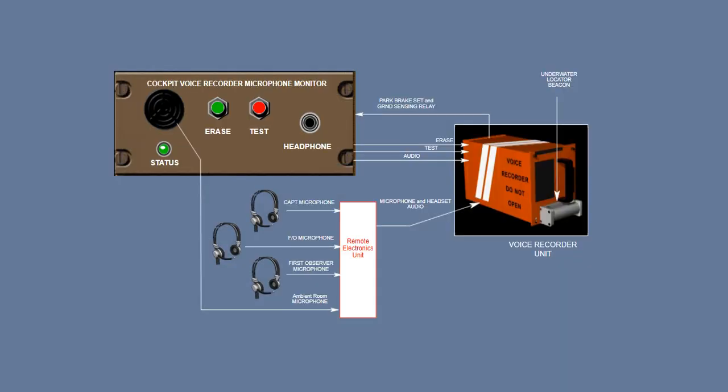The cockpit voice recorder has 4 recording channels to record audio conversation from various microphones. It is powered whenever normal AC power is applied to the aircraft. The recording tape is a perpetual tape that is overwritten by new recordings every 30 minutes. Thus, recordings of up to 30 minutes are available, and earlier audio is automatically erased.